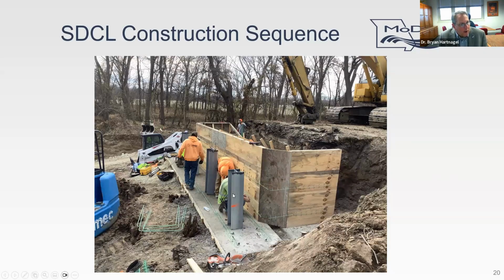After you've driven the pile, and for the last probably 10 to 15 years, we've been galvanizing the H pile that we use down to the scour depth. And generally that may be 20 to 40 feet. If you've got a 100-foot pile, we'd allow the contractor to drive the first 50 or 60 feet of black steel pile and then weld on a galvanized one for the top. But so they've driven the pile there.